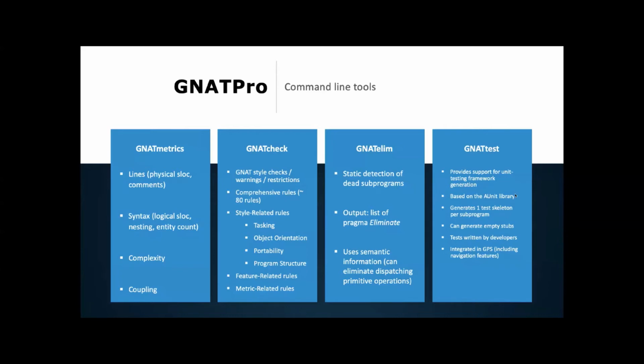There are cases where if you use GNAT-elim, you might want to verify the output of GNAT-elim. For instance, let's say you have an interrupt handler. That interrupt handler looks dead, so GNAT-elim will flag it and say this is dead because there's no call anywhere from the main application. So this is a case where you have to go in and say, hey, this is actually something I need in my application. Please don't strip that.